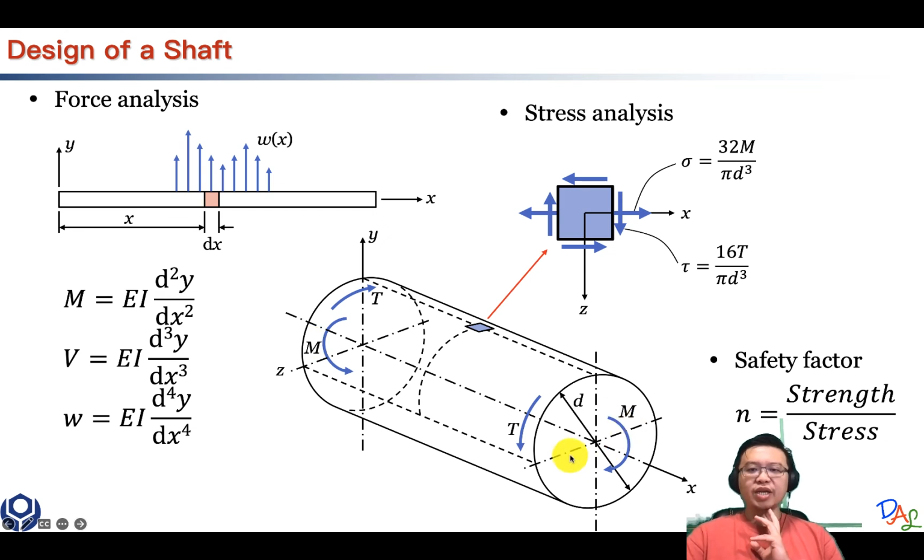When a beam is under more complicated load conditions, M and T cannot be calculated easily. So how do you do that? You can perform force analysis along the beam, like what we did earlier. Due to some external loads, we need to know how much shear and how much moment was caused onto that small portion. With those two very important pieces of information, we can then calculate M and T at a certain point.